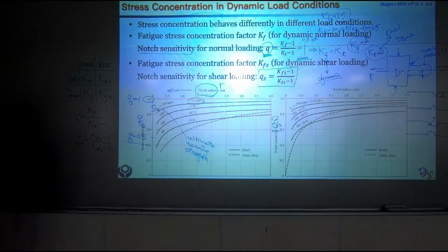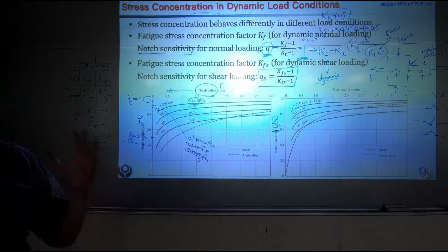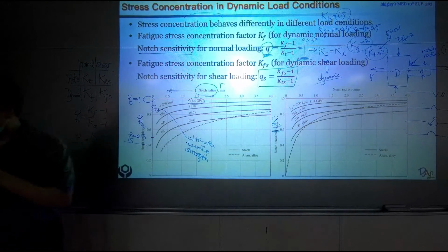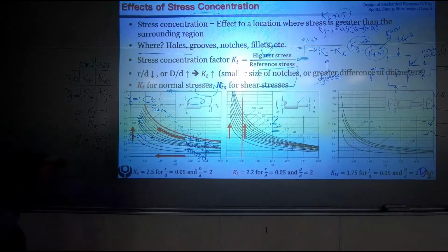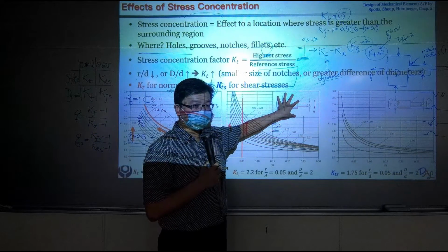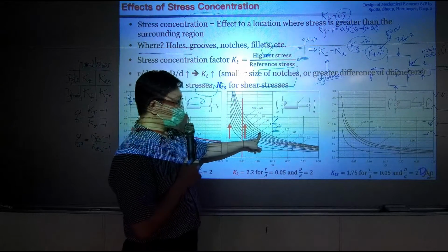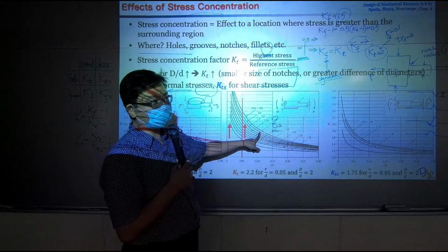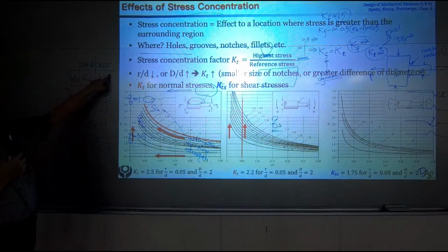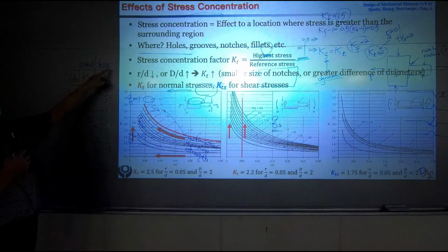So the procedure is, when you are concerned about stress concentration, you can check the first several tables here to study what kind of loading case you're having and what geometrical parameters you're having. Then you can estimate your K. So you will either have Kt or Kts, depending on whether you are having normal stress or shear stress.